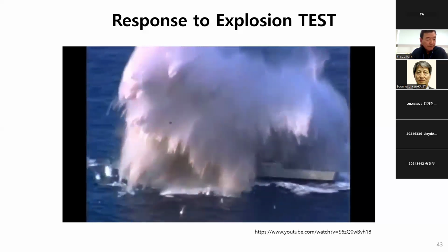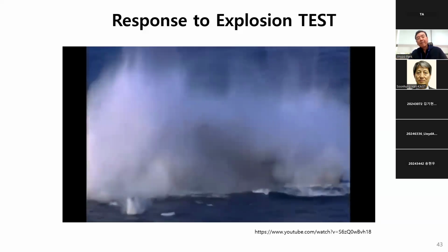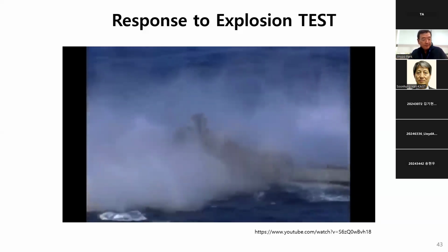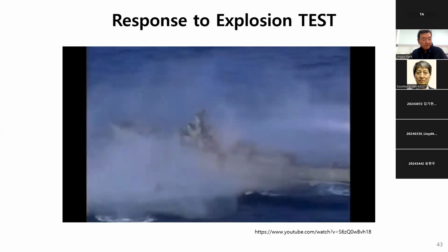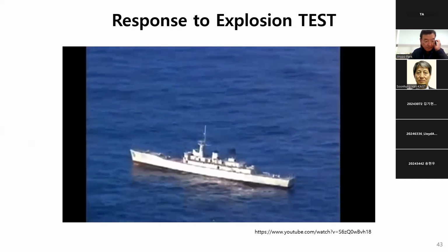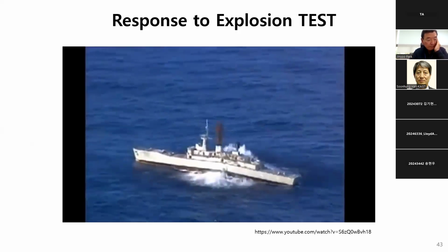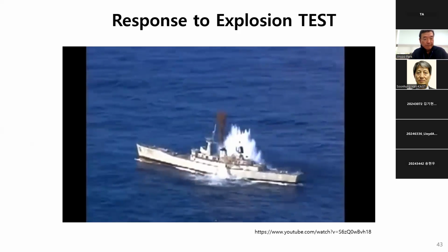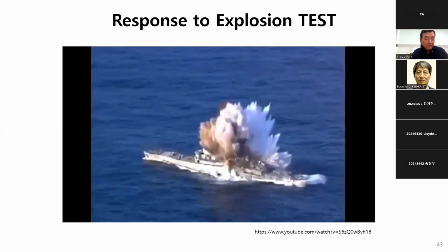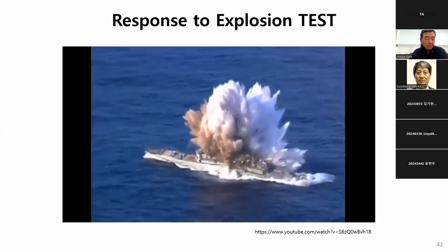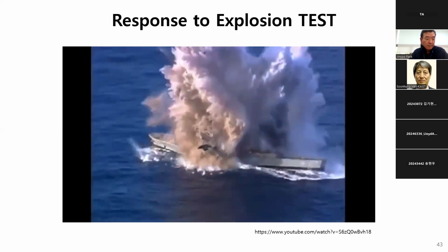This detonation vaporizes the water around the torpedo and creates a high-pressure, high-temperature steam bubble, as well as an intense shock wave beneath the keel. When the detonation occurs below the keel, the resulting pressure wave of the explosion lifts the ship, weakening its keel in the process. As the steam bubble collapses, the ship is sucked down by negative pressure and appears to momentarily sag in the middle. When the steam bubble finally reaches the surface, it explodes through the hull of the ship as the change in pressure creates another more powerful shock wave. This combined effect often breaks smaller targets in half and can severely disable larger vessels.